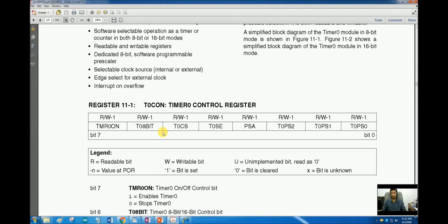In case of timer 0, we know that there are two registers, the TMR0H and TMR0L. These two count registers combine together to form a single pseudo 16-bit register. That is not an actual 16-bit register because our microcontroller is of 8-bit size. So what happens is, at physical level, there are two different registers, one an 8-bit lower register and one an 8-bit higher register, and to read or write any of those registers, we need separate clock cycles for both.